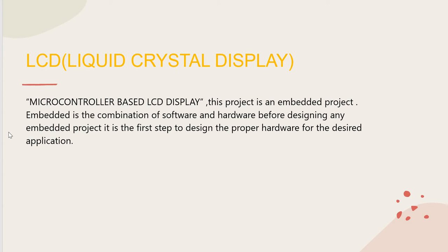Here we are interfacing the LCD with the microcontroller. We are using the ATMEL series 51 controller, the 89C51, a 40-pin IC. The first step while designing hardware is to design the required power supply, as the controller operates on plus 5 volt supply. So first we have to design the regulated supply with the help of transformer, regulator and filtering capacitor. Next step is the necessary connection of the controller, like reset and the crystal oscillator, for resetting and speed respectively.